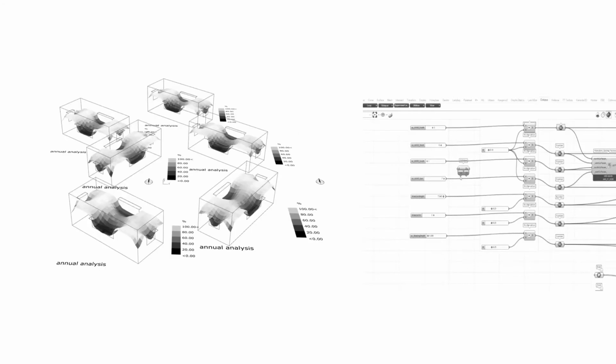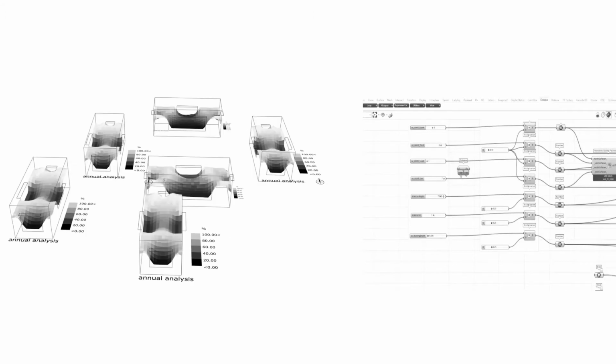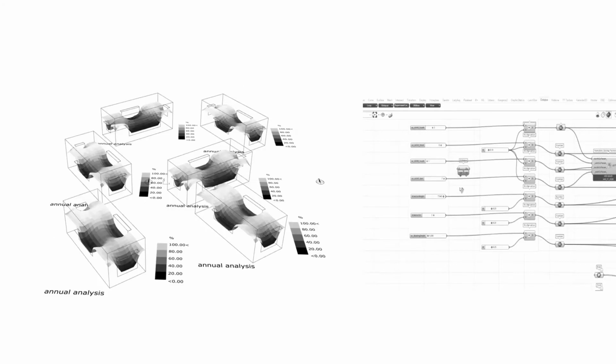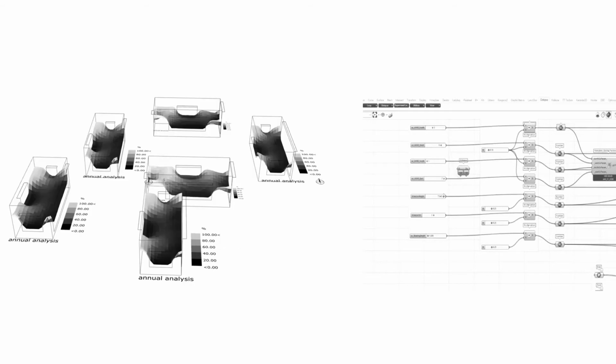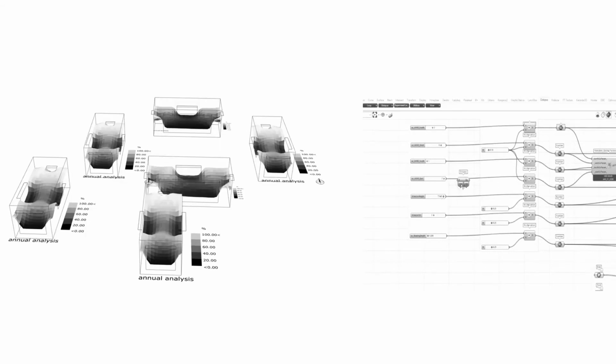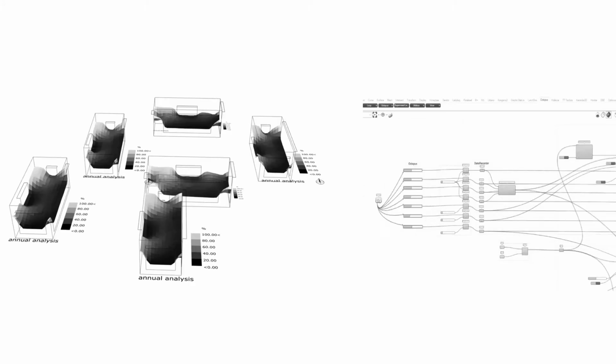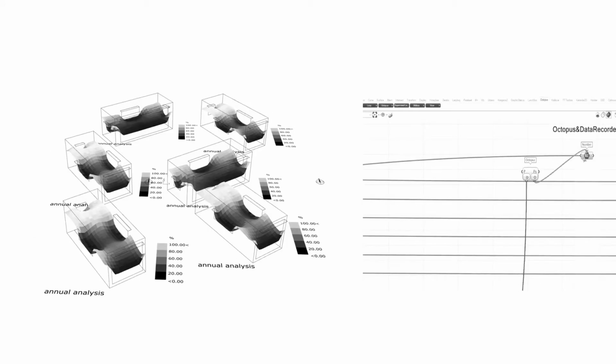We chose several design variables of container housing units for the multi-objective optimization process. The design variables were window-to-wall ratio for 4 elevations, window height, window sill, module orientation, and shading depth. We determined the range of these design variables through the physical survey in the slum and local building construction regulations.